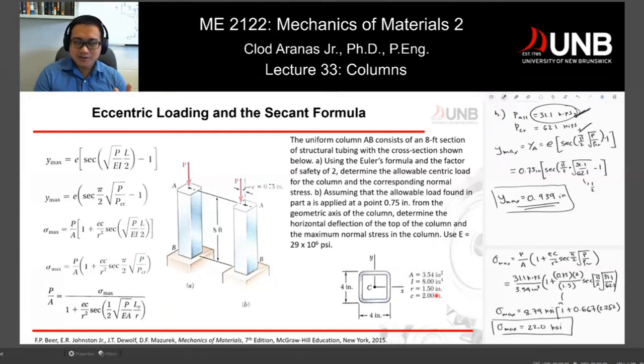Let's say what's the force to buckle it, which is based on the column. What's the force or stress to yield it? And it's just really your yield stress. You have a yield stress, you have an area, you can calculate the critical load in order for you to yield or deform your material. So I think that's the only critical part. But other than that, everything is almost kind of plug in, and then you have those numbers. And that's it for columns.